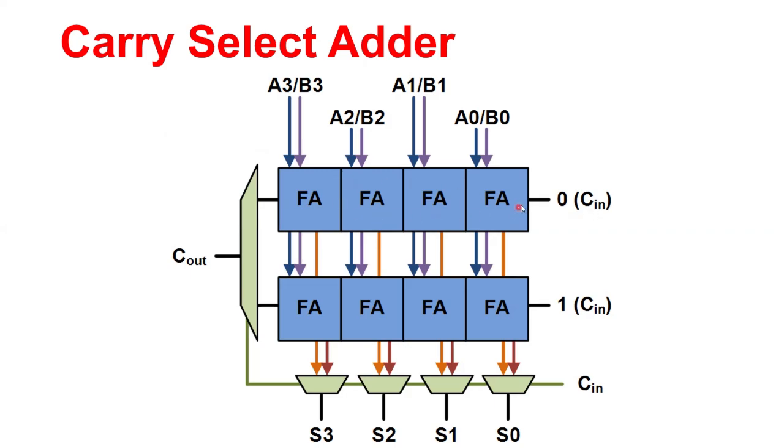So, for example, this is, let's say, a one bit full adder circuit. This is another one bit full adder circuit, and so on and so forth. So, let's say the 4-bit adder example here. Here goes the carry in, C in, and then it has the output of the adder circuit in the form of sum, the orange line, and its own carry out, which becomes a carry in to the next stage.